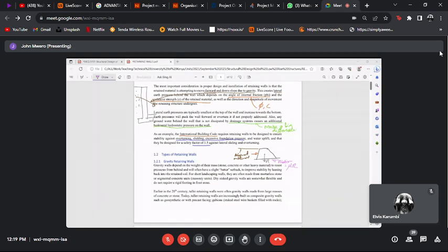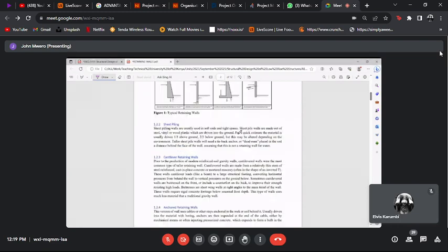Okay, so the other type of retaining walls is what we call sheet piling. So you've got thin corrugated sheets. So you corrugate them that way. Thin steel sheets, so you give them ridges like that. So this sheet would be maybe 1.5, 2 millimeters for the sake of this discussion. Okay, let's assume it's 2 millimeters.